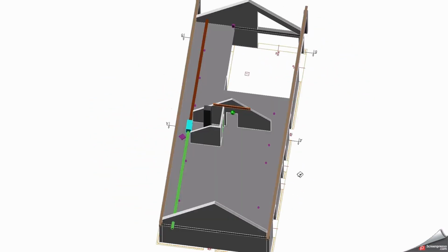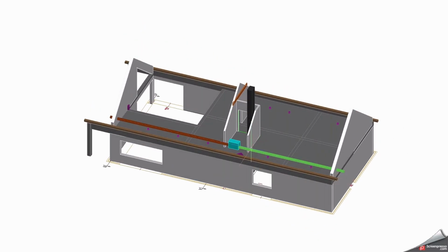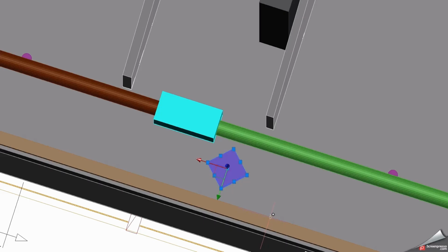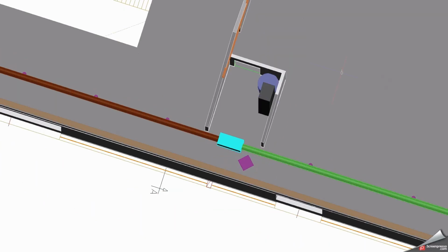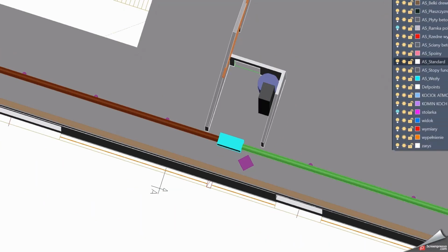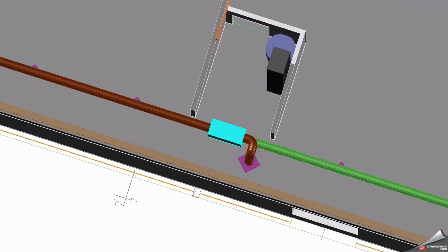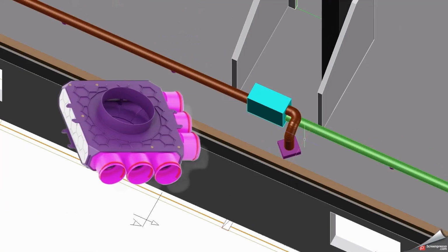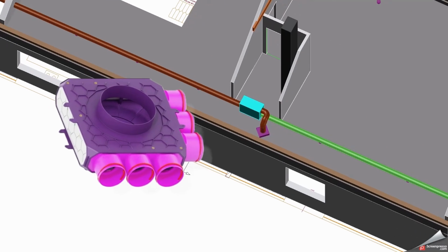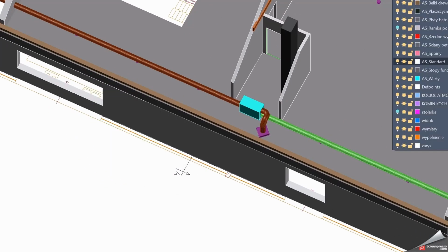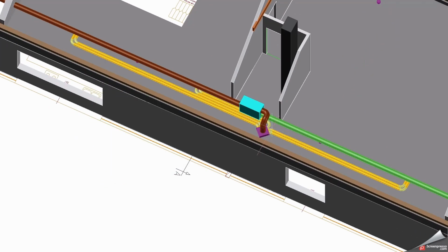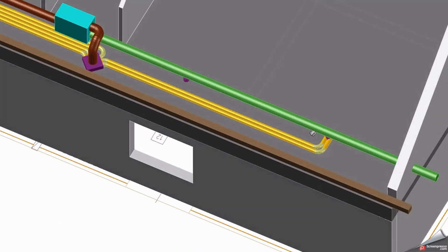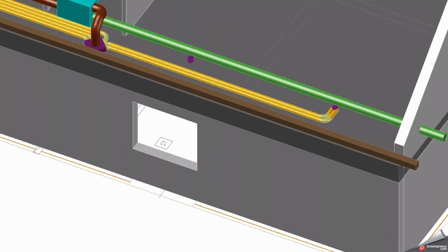Next, we positioned the distribution boxes, starting with the exhaust boxes from the dirty rooms. In our specific case, we have 3 rooms, 2 bathrooms and a kitchen. All the soiled rooms are located in the eastern section of the building. Each of these is connected by means of 2 pipes. Here we have implemented a single, non-flow-through expansion box with 6 outlets for 90 mm diameter pipes. Because on one side we required 2 channels and on the other 4, the box was then rotated by 45 degrees to minimize the pipe bends.